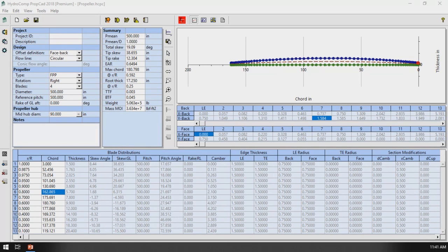So for instance, if you're using SolidWorks, I'd recommend exporting the SolidWorks macro. What that does is it rebuilds your geometry natively using SolidWorks loft and surface commands and all those good things, so that your geometry is built up natively in the CAD program, so you don't have any troubles when you go to CAD CAM or CFD.